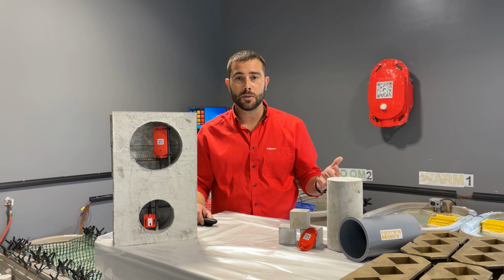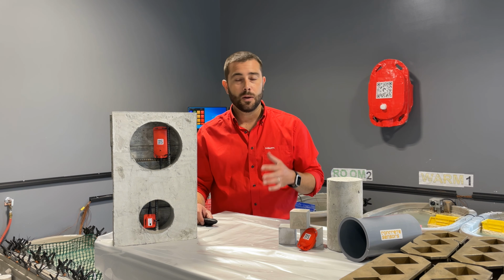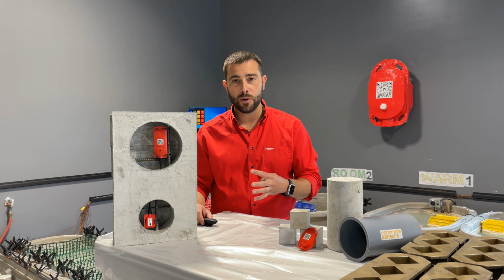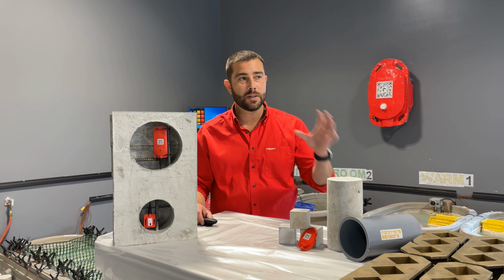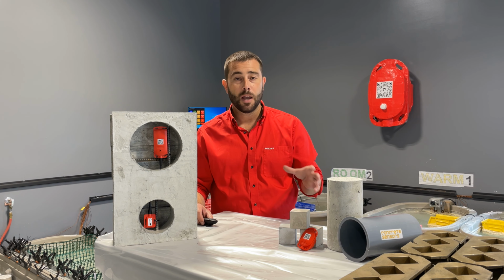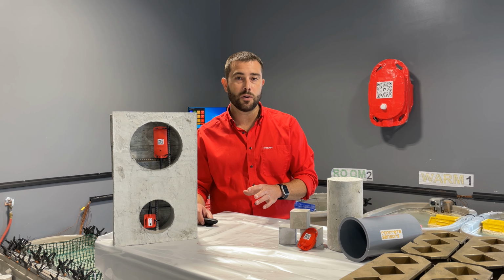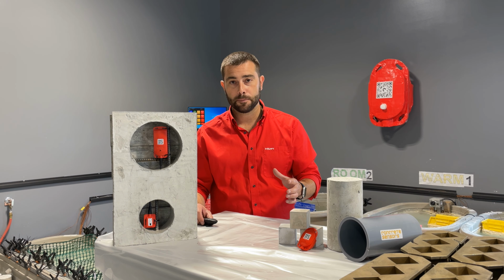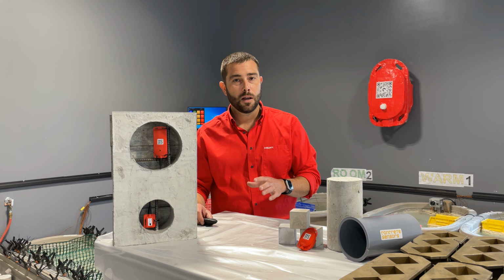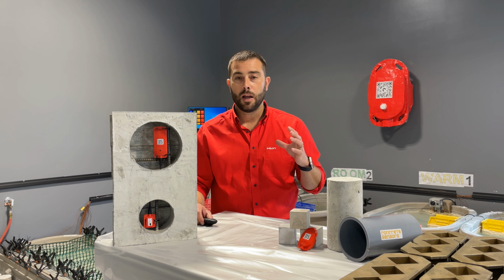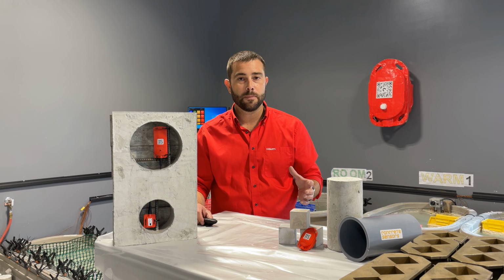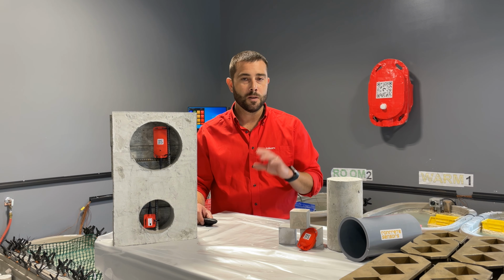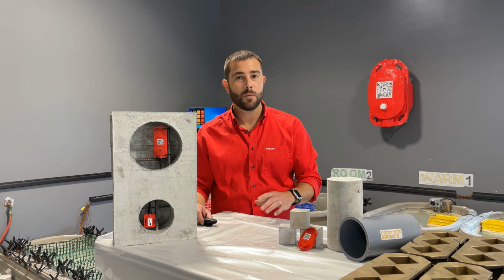Here at Concrete Sensors Lab, we'll test or calibrate your mix at 4 different temperatures. We do this because the temperatures in the real world vary. It also helps give us the most accurate strength curve we can get. Once you've got that done, grab some sensors, activate and install them on your site, pour your concrete, and then the sensors in the app do the rest of the work.